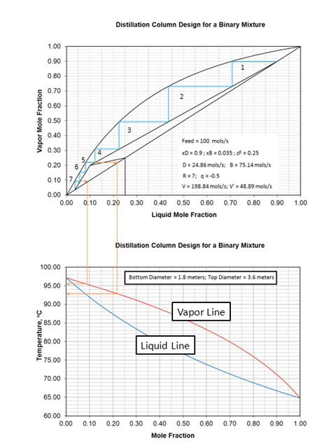Also, let's look at one feature on this that will allow us to determine the temperatures of each individual stage. If we look at the point on the reboiler, the last stage, stage 7, we know that the mole fraction in the vapor phase is approximately 0.08. If we take that over to the y equals x line, as you see in gold, and then project that down to the vapor line in the bottom graph, we will find that that intersects at around 95 degrees Celsius